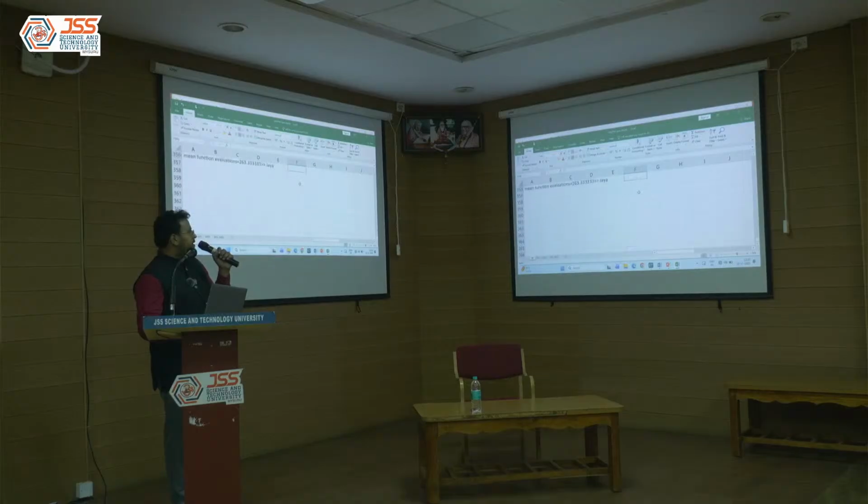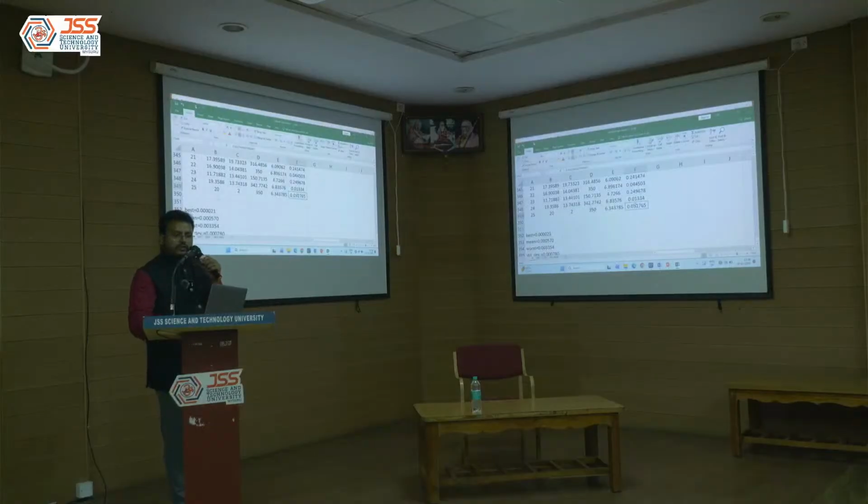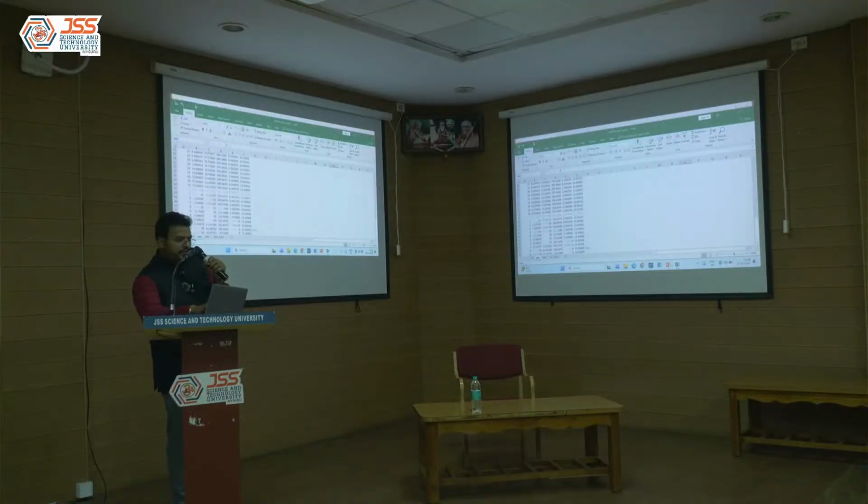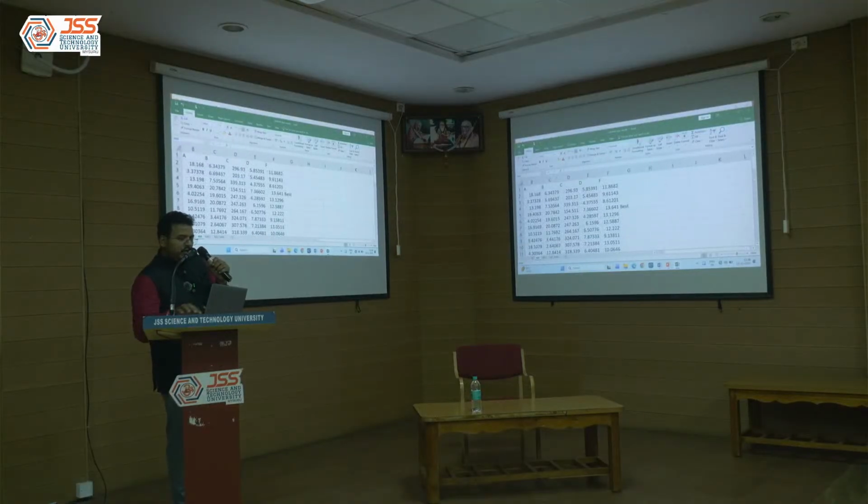Optimum results finally, the best solution is this: you use 20 kilohertz frequency, 350 abrasive size, and 2 minutes of processing time, and you will be getting the best solution. Similarly for MRR, you see. For MRR, let us say higher is the best solution and lower is the worst solution.